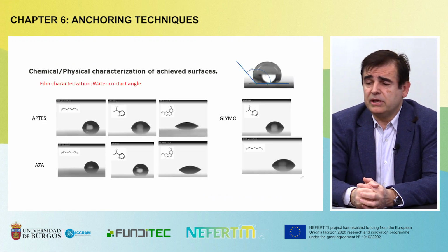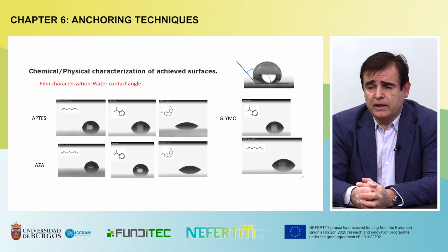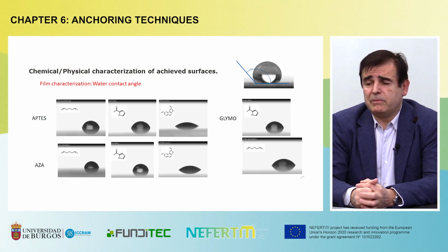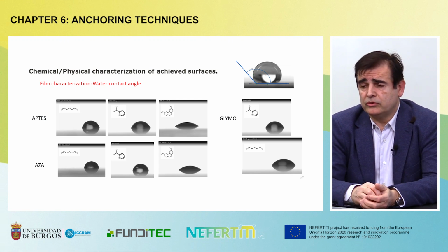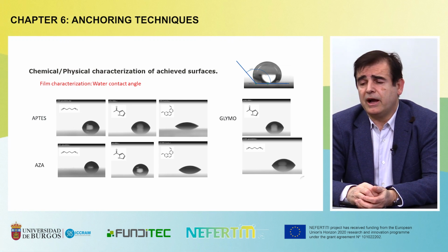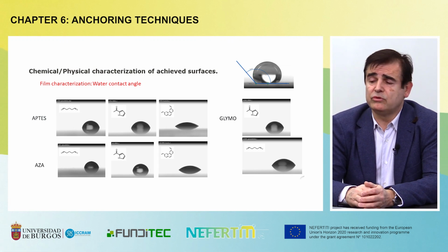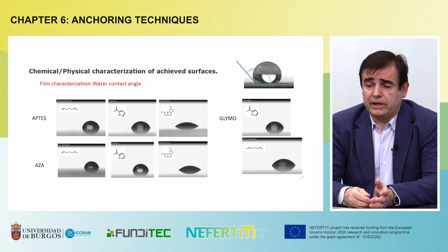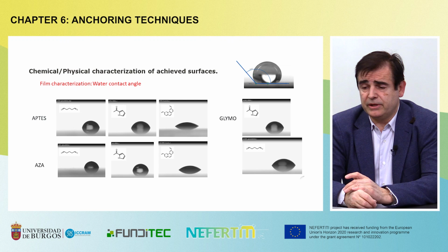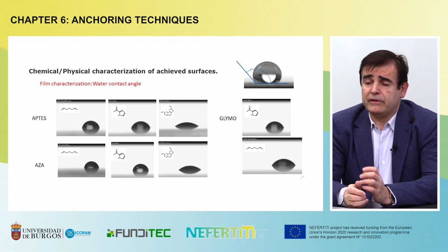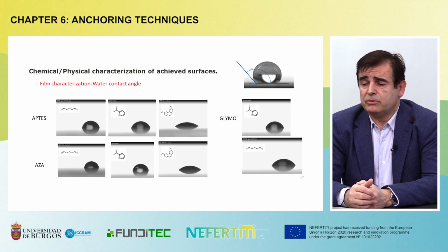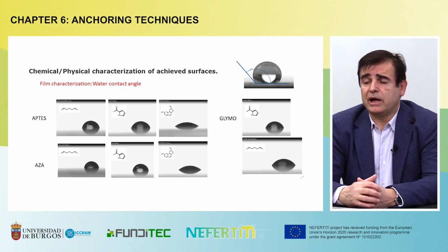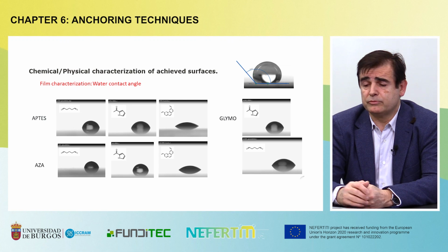This technique can be seen clearly in the following picture. This technique consists of application of a micro drop of water on the surface to be tested and measuring the angle formed between the activated surface and the external profile of the drop. The higher the angle, the lower the hydrophilicity. In this example, it's easy to see, and in a direct way, to control the deposition of the different layers that can form a catalytic surface arranged on a substrate.